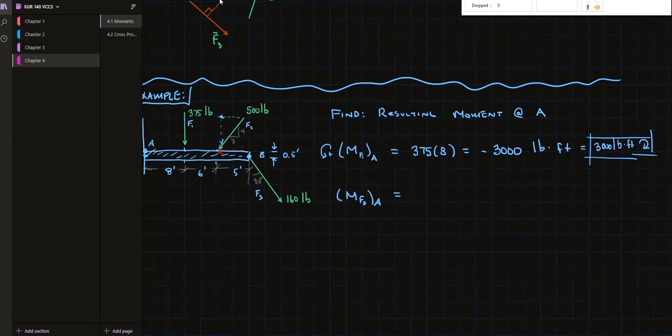So the vertical component, and that is proportioned as 4/5 of 500 times our moment arm of 14. I always forget to add the moment arm, and that's an easy thing to do for everybody. So 400 times 14 is going to be 5,600 pound-foot. And again, that'll be acting in the negative direction.